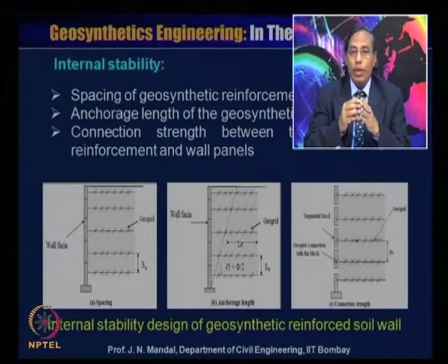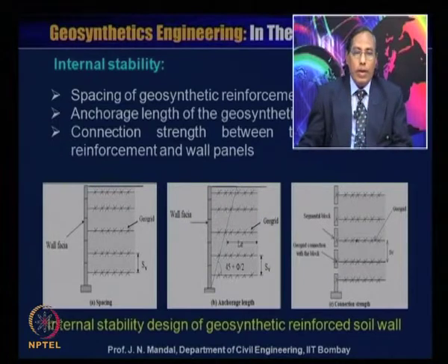These are very important. Most of the time we don't consider the connection strength, but the structure may fail if you don't consider the connection strength between the reinforcement and the wall panel or the block. So there is a possibility of failure due to slippage, and failure due to the connection. So you have to properly design for internal stability. So you need the spacing.